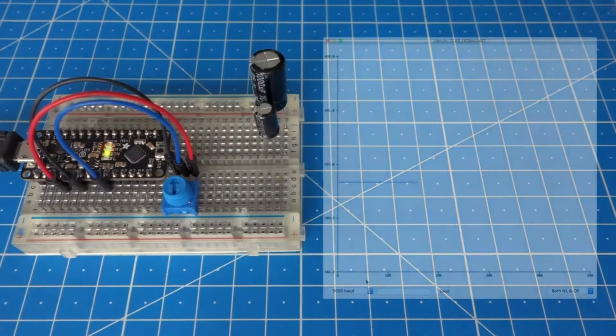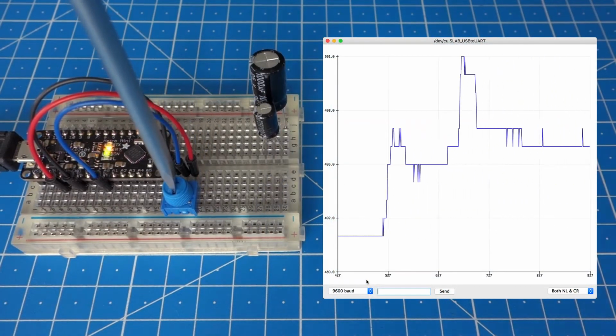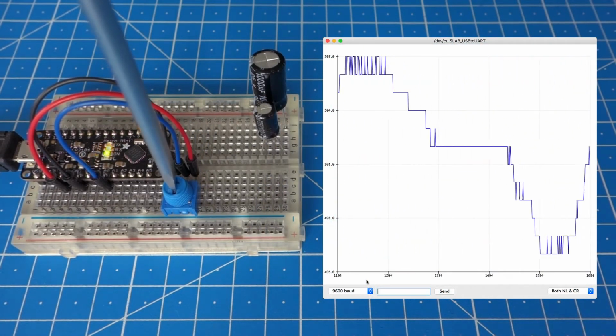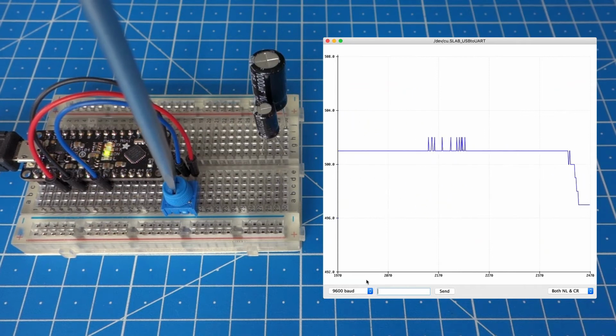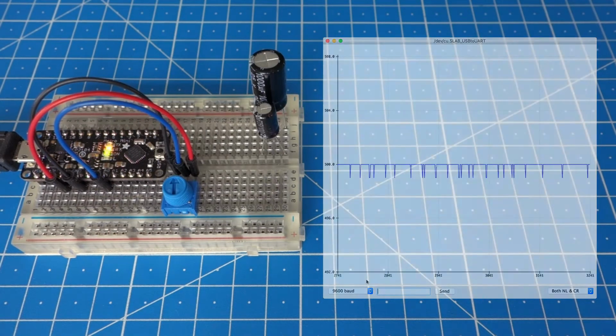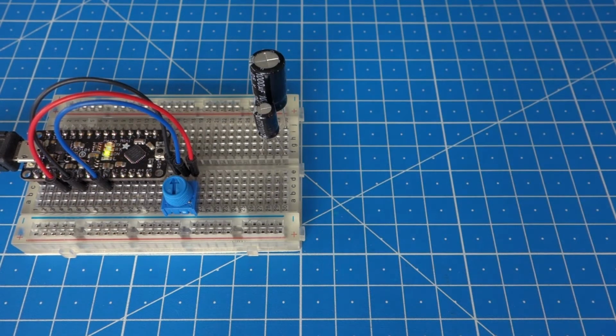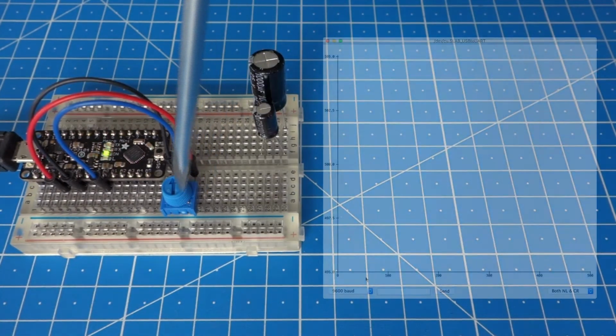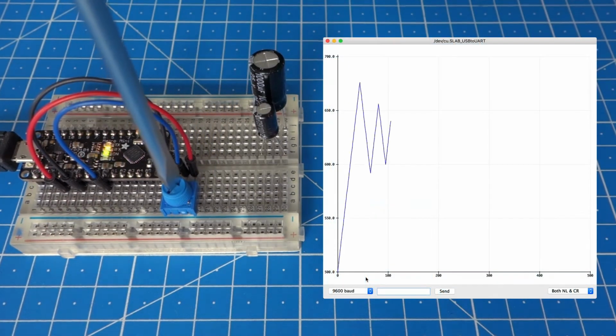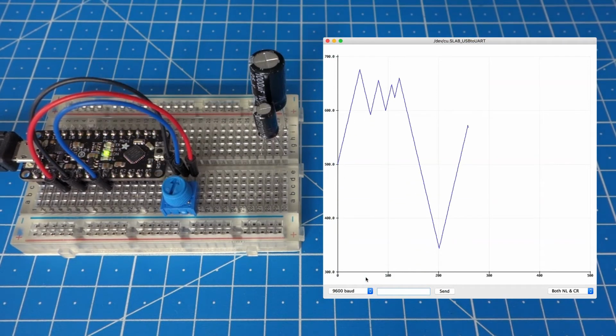The next tip shows you how to study the analog input from a potentiometer or sensor that will always fluctuate a bit, as you can see from the spikes in the serial plotter. When you exclude value changes of 1, 2 or 3, depending on how much fluctuation you want to suppress, the analog input becomes nice and steady.